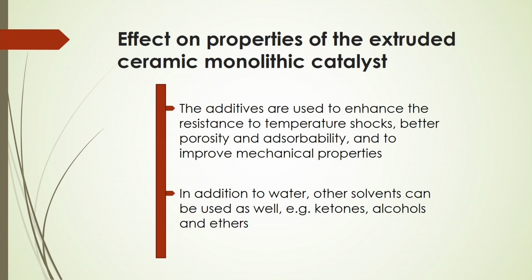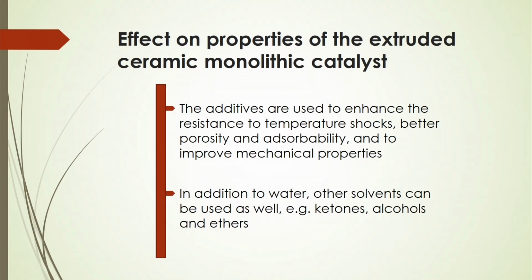And the additives are used to enhance resistance to temperature shocks, for better porosity and adsorbability, and to improve the mechanical properties. So, you have to remember to use suitable additives where you can enhance the resistance to temperature shocks, better porosity and also adsorbability. And I told you that in addition to water, other solvents can be used as well, so that you can get a more stable structure of the monolithic catalyst. In that case, ketones, alcohols and ethers can be used along with water.